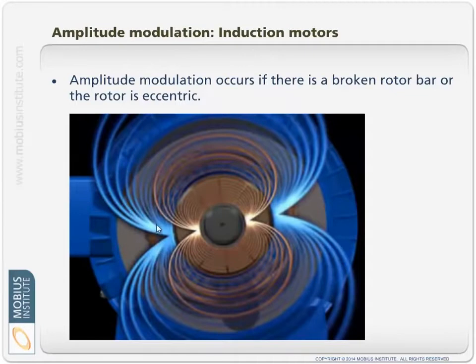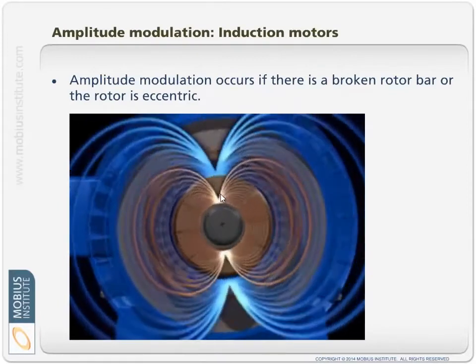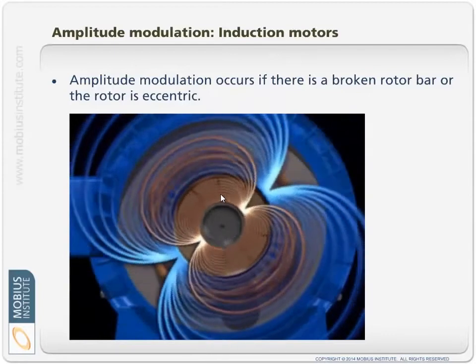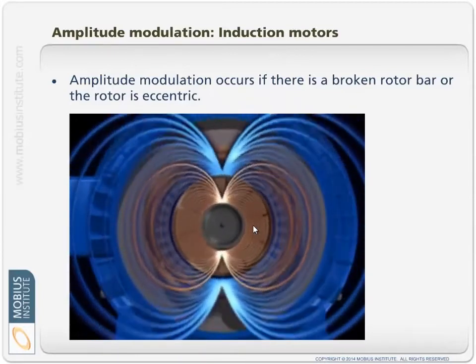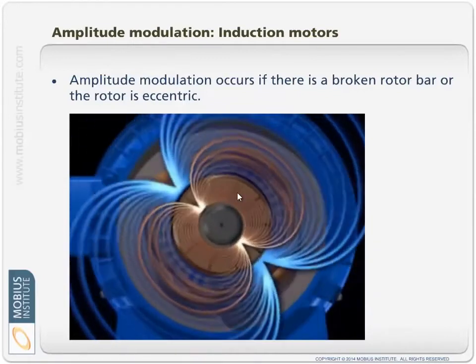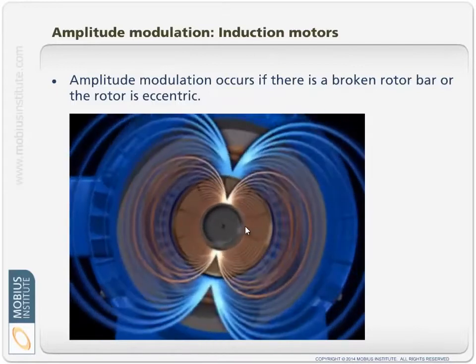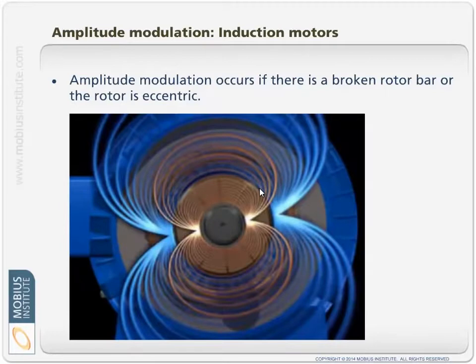That's what the blue wave is here. It's like the north pole, the south pole, two poles, north, south. That rotating magnetic field induces a current in our rotor. And when you induce current in the rotor, it also generates a magnetic field. That magnetic field sees the rotating magnetic field around it and tries to chase it.